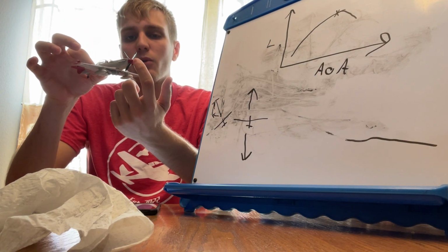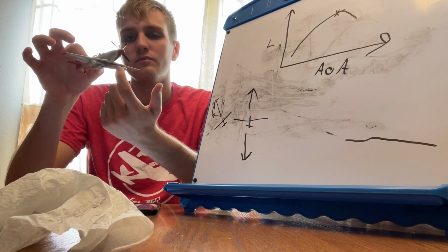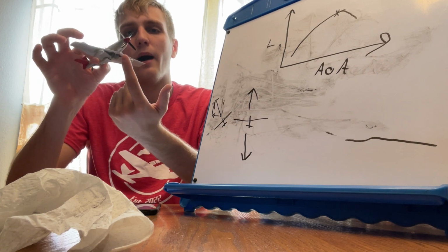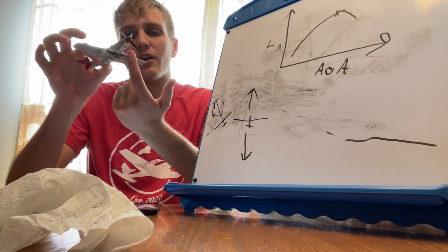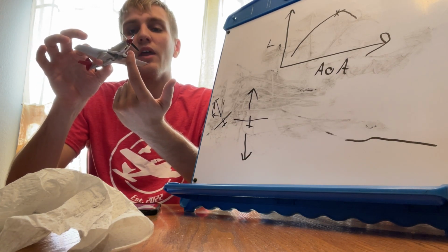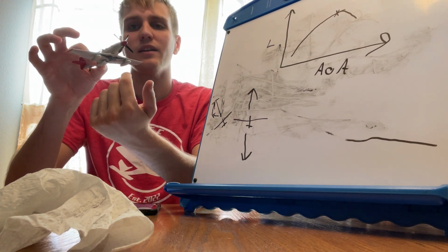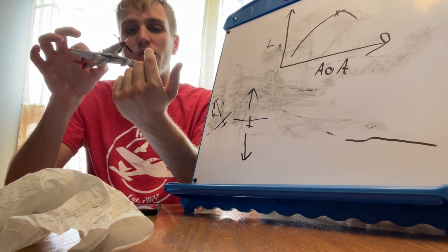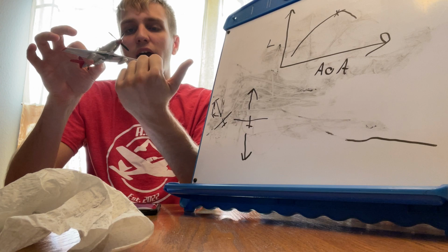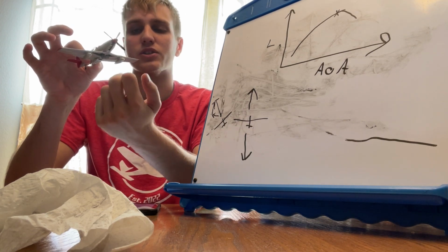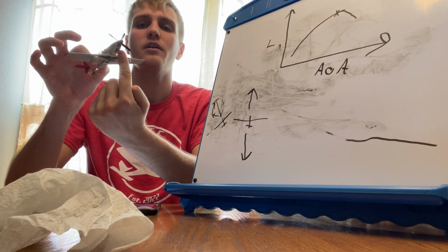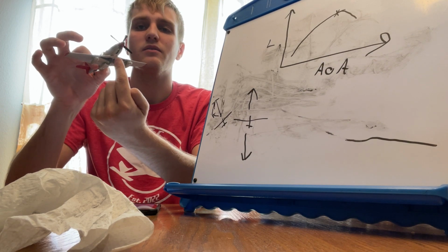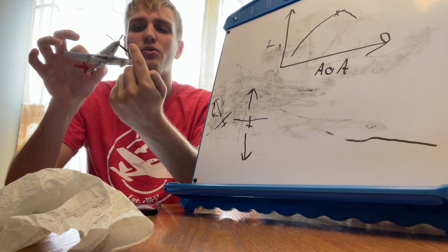When you apply a force, say we apply a force up on the airplane, gyroscopic precession means that we will have an extra force 90 degrees ahead with the rotation and in that direction. So if we push up, with the prop spinning this way, 90 degrees of that rotation puts you on the left side of the airplane.